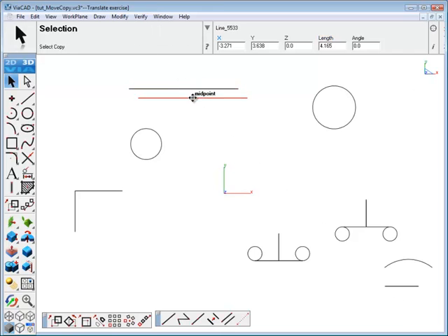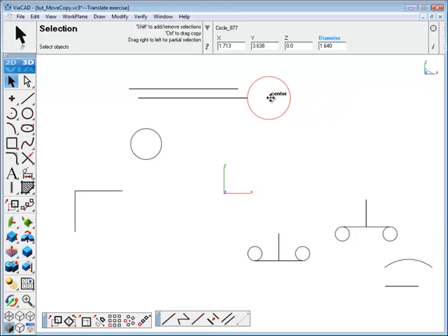To drag this circle, we'll position on the quadrant point and drag to an end point, or position the cursor at the center point. Notice in the data input window that circle is defined by its center point. That's its coordinate. As I move the circle, we'll position the center over the origin and the data input window will show 0, 0 as its x and y coordinates. Changing the value changes the actual absolute coordinate for the center of that circle.